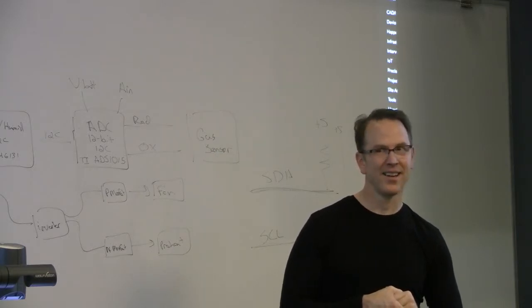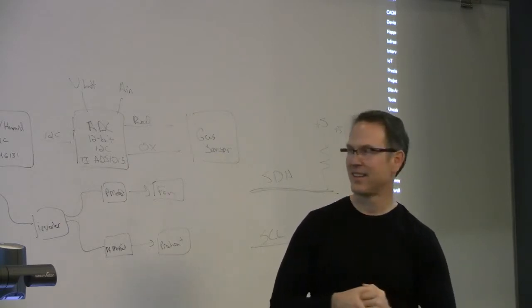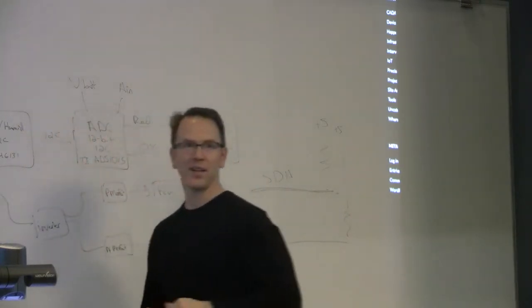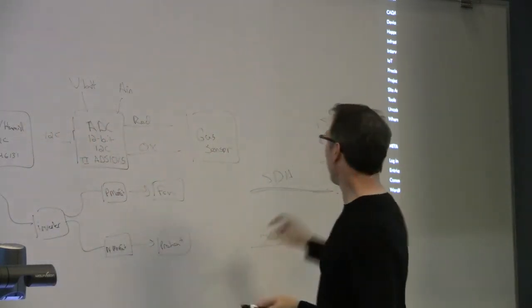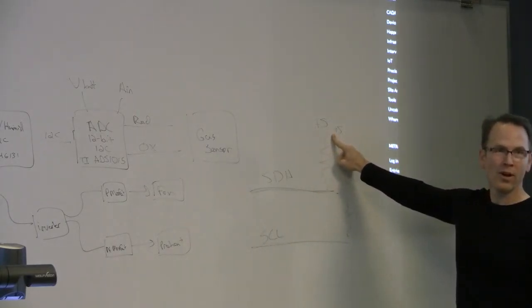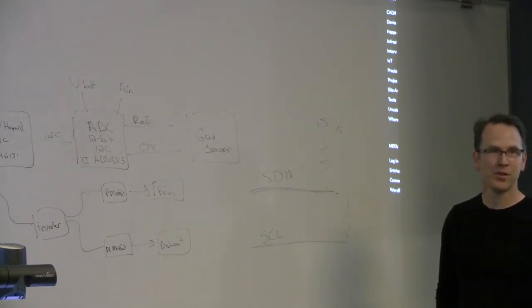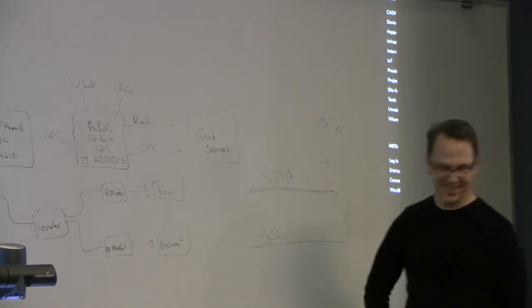I'm never going to send 5 volts to my Pi. It's got 2 wires going from the port expander to the Pi, SDA and SCL. And somebody is pulling those up to some voltage. It's either done on the Pi end to 3.3, or it's done on the port expander to 5, or both, which would probably be bad.